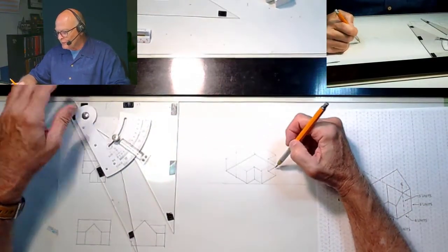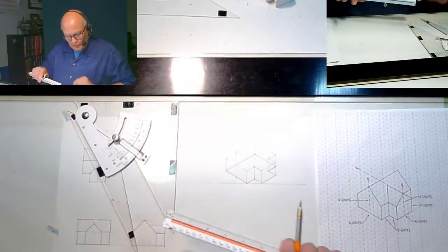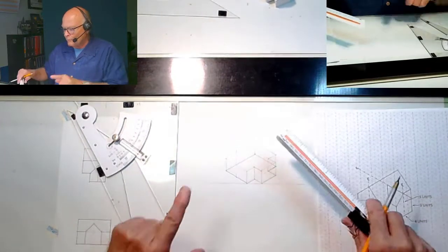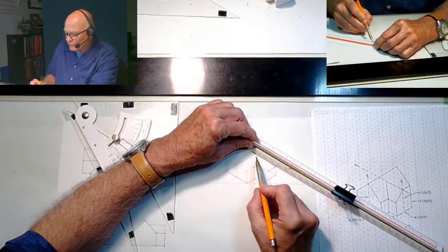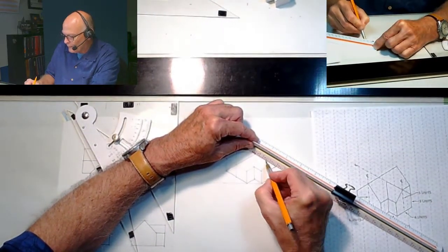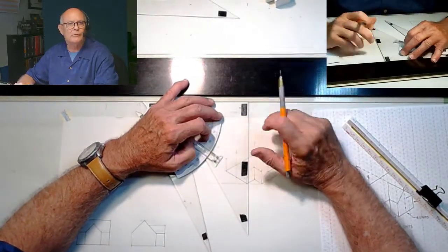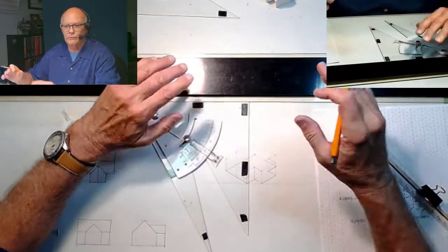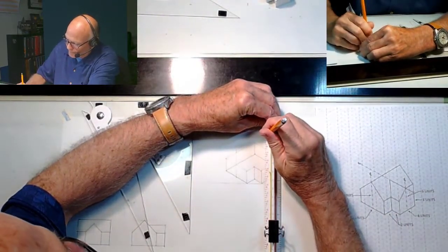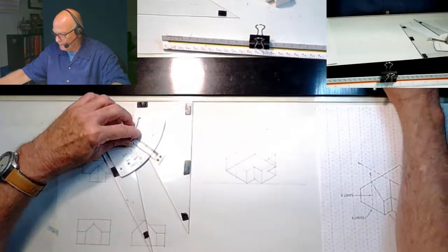So we're going to do the same thing on the back side. This line across here, which is hidden here, but is symmetric on this element here, we can do the same thing. So I'm going to measure from the back corner forward 3. And I'm going to draw a vertical line. How high? 6. Same as the other side. Again, symmetry. So we mark that there. Now, go ahead and clean up the tail on that.